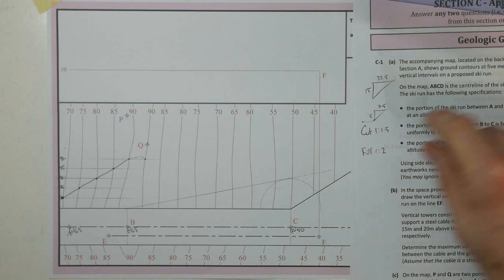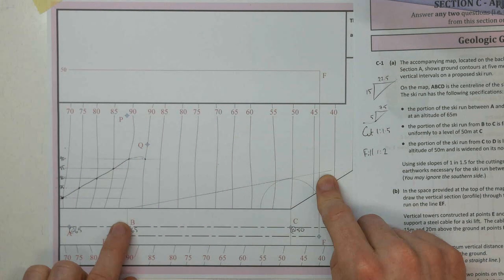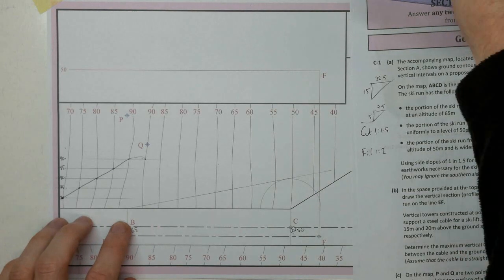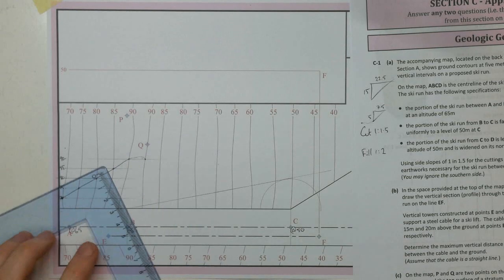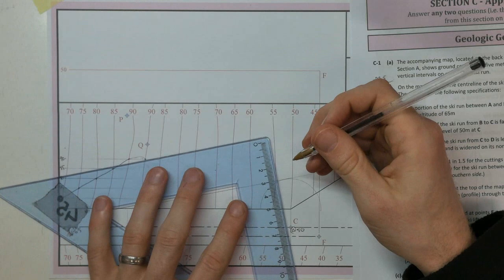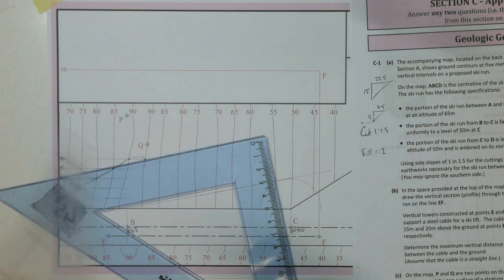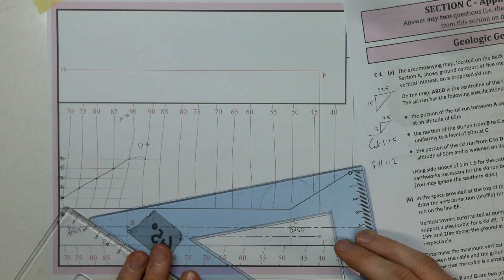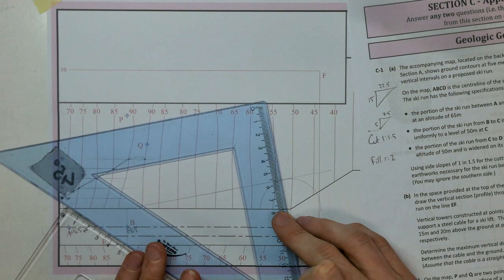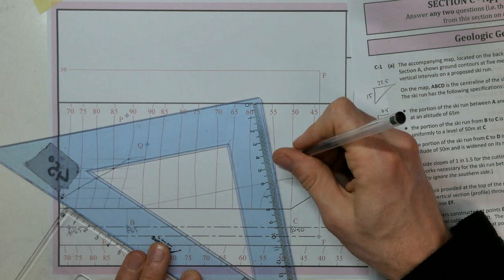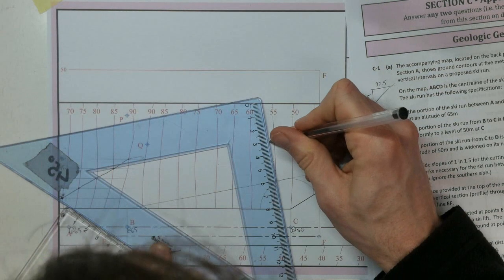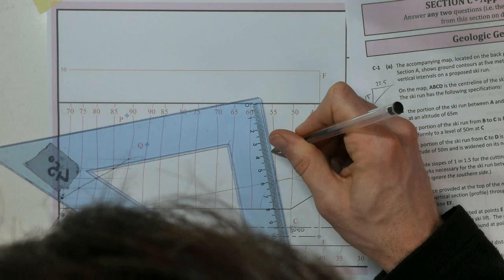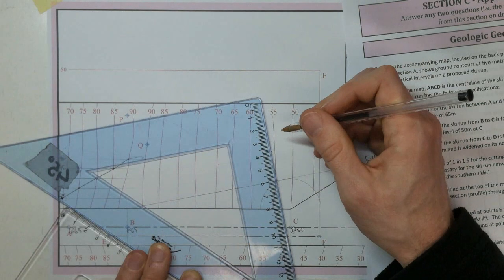And that is 65, so that's at a height of 65. We're cutting again, so it's 7.5 meter intervals, similar to what we did over here. I'm measuring at 7.5, trying to do that perpendicularly. Halfway, 50 and halfway.